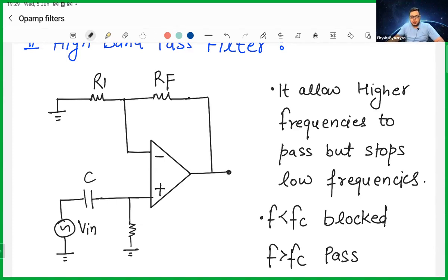Okay. So how is this high pass now? Let's say I send a low frequency, and immediately in front of me there is a capacitor. Before, there was an option after some time that I can go to a capacitor or I cannot go to a capacitor. But now there is no option. I have to pass through the capacitor anyway. So there is a capacitor directly in front of me and I send low frequency. This capacitor will say, no, I don't allow low frequency. So low frequency will never reach. But if I send high frequency, this capacitor will say, okay, let it pass. So that is the difference.